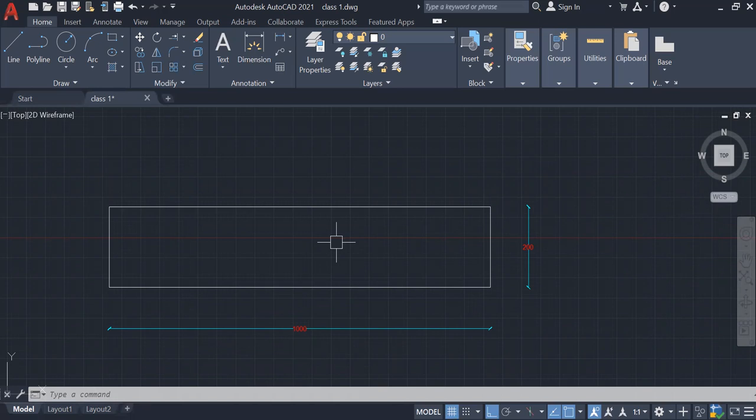Okay, because otherwise, if you go for the 1:100 scale, then the working drawings will not fit in the particular drawing sheet. So for that purpose, we are using different scales. Otherwise, that much big size of drawing sheet is not available. We can't fit that one. For example, the length is 1,000 meter or 1 kilometer. If you are going for city planning, correct? If you are going for town planning, in that case 1:100 scale is not useful. In that case, we go for 1:1000 scales. 1 meter equal to 1,000. Like that, we need to go for that.